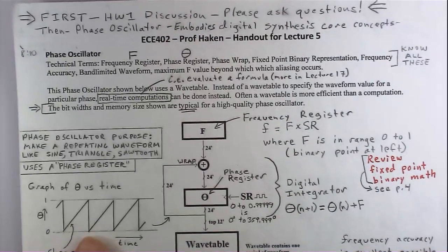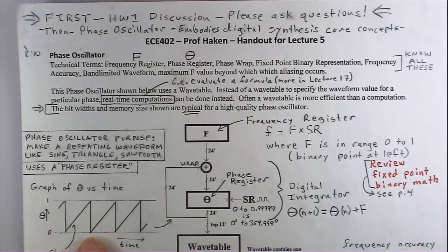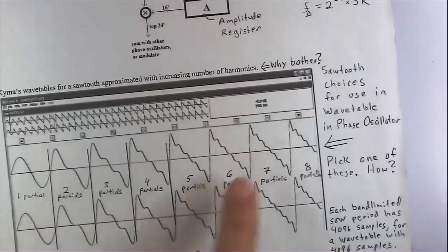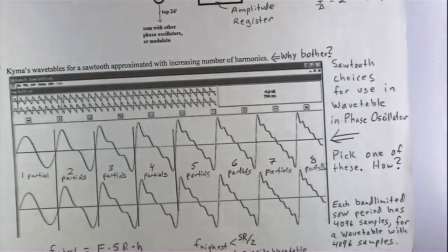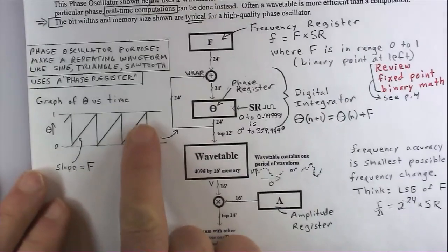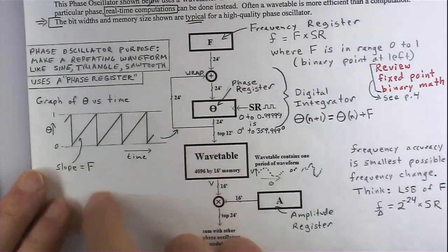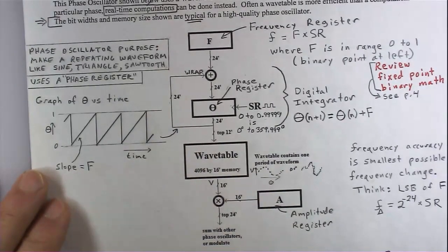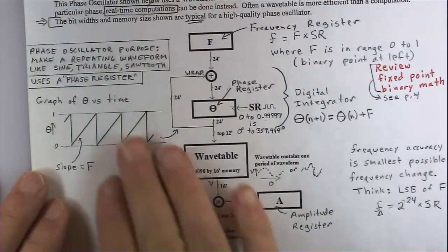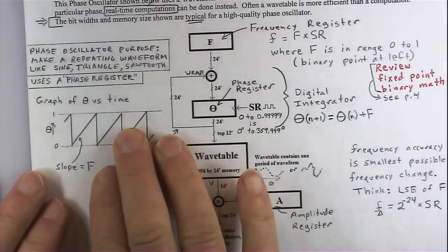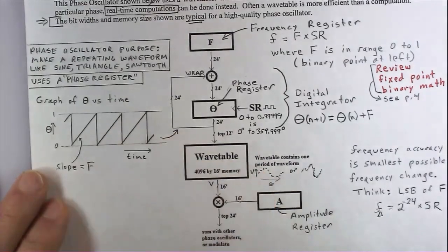You don't want to make a sawtooth that looks like that in digital and stick it to your DAC. You always make a sawtooth that looks like one of these wiggly dudes. Right? And why is that? Well, you can't have any sharp corners because you can't have frequencies above the half sample rate. And if you say, oh, but I do have frequencies above half sample rate, see this corner here? See, that's sharp. And this is a digital signal. Well, you're fooling yourself. You're misinterpreting it. What that represents is an aliased piece of garbage.